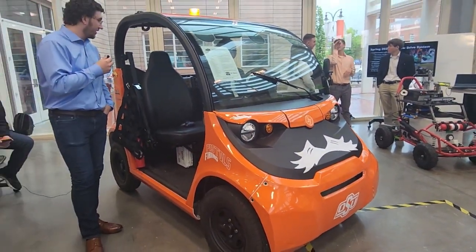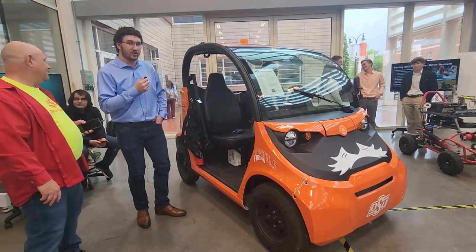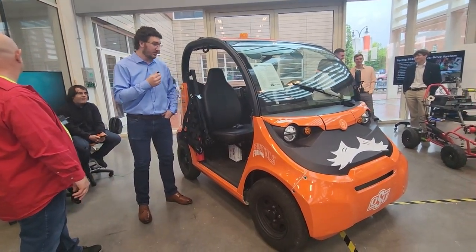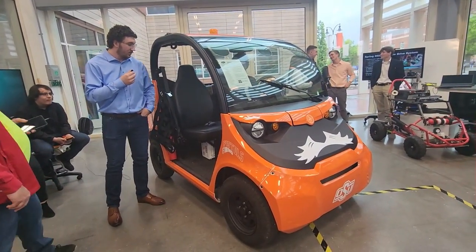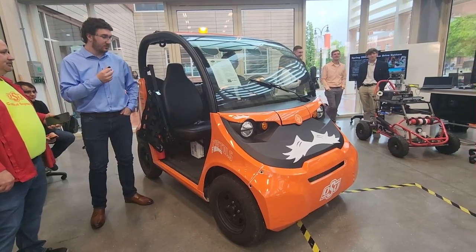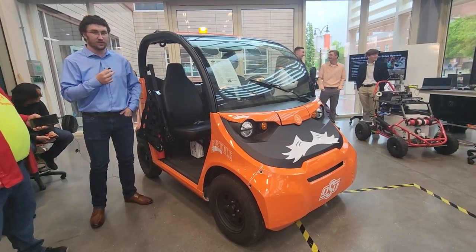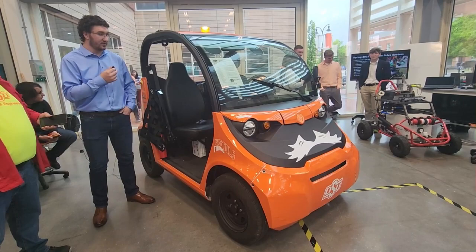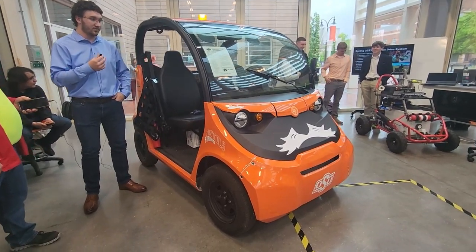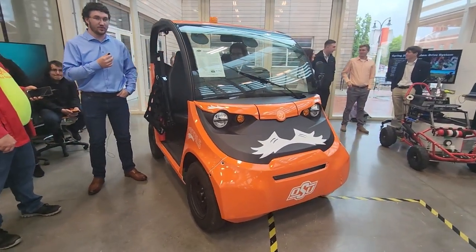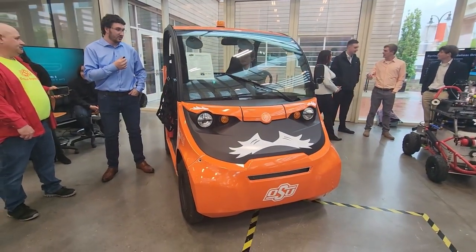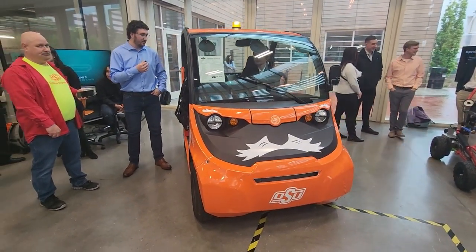Inside of the vehicle, we have our custom drive-by-wire system to control the vehicle remotely, as well as an onboard computer that runs ROS that integrates with all the sensors and the drive-by-wire system over CAN to actually control the vehicle. And it's all interfaced with the GUI that we have built into the dash to make it a clean and professional look.